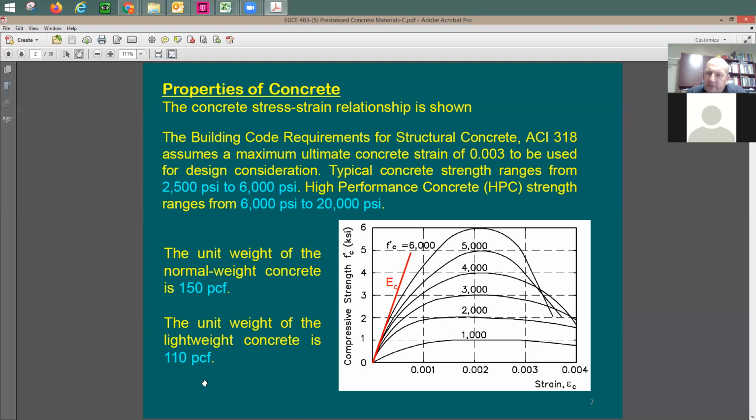So just imagine that you don't have any columns. And then at the end of this double T, you're going to have a line of beams, columns, and also you're going to have the lateral system. Most likely it's going to be either shear walls or reinforced concrete, pre-stressed or non-pre-stressed moment frames. Seismic, as you know, is going to be related to the weight of the structure. When you have higher weight, seismic force is going to be large, and you're going to be in trouble just to make it work. So you better try to reduce the weight of the structure as much as you can in the main elements.